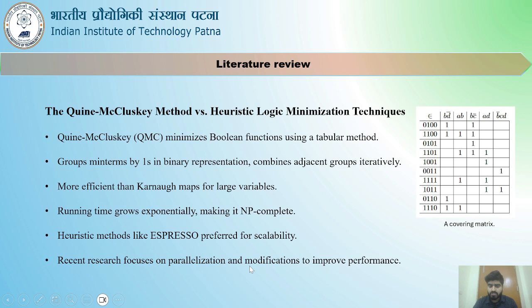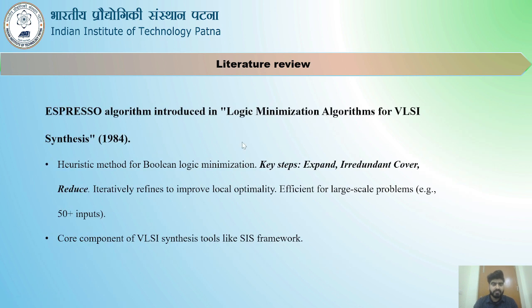Recent research focuses on parallelization and modification performance. The next literature review is the Espresso algorithm, introduced in "Logic Minimization Algorithms for VLSI Synthesis" in 1984. It is a heuristic method for Boolean logic minimization, and the key steps are expand, irredundant cover, and reduce.